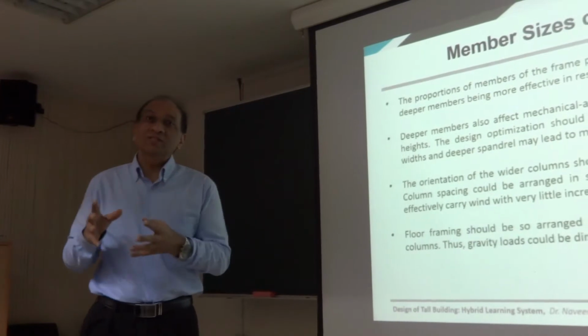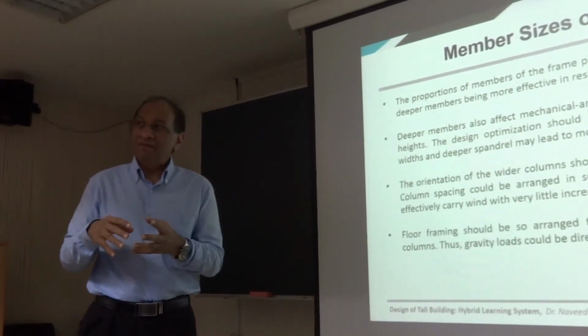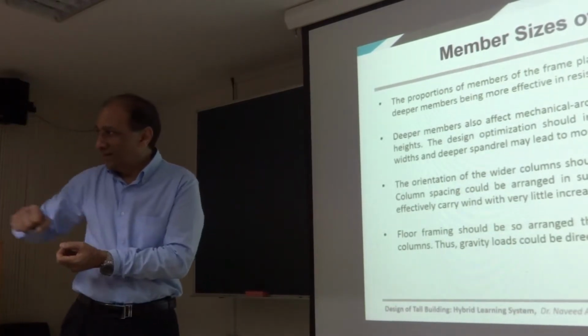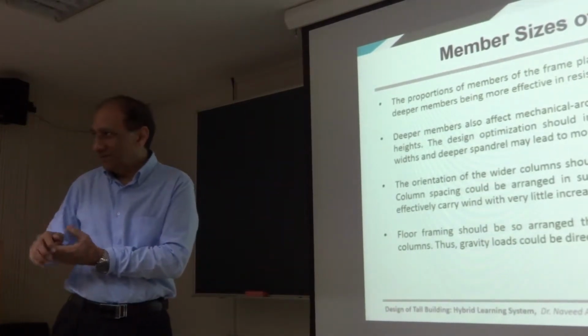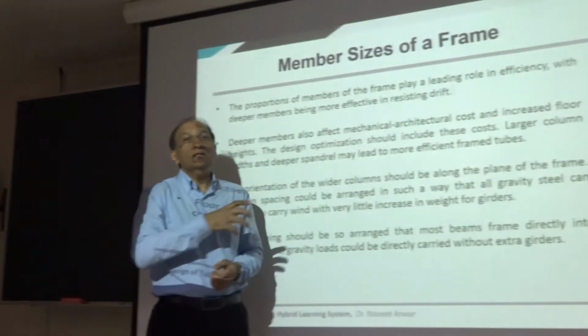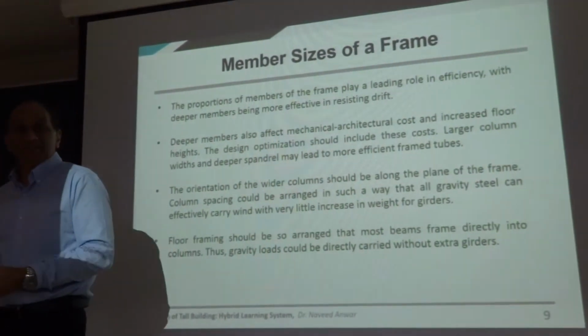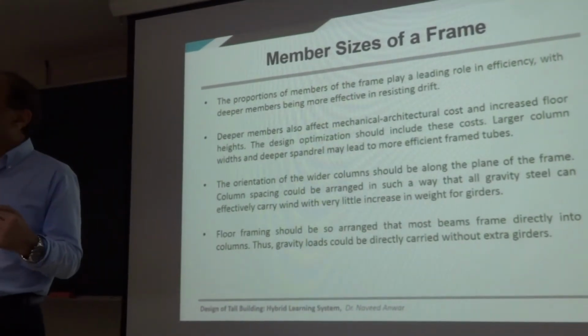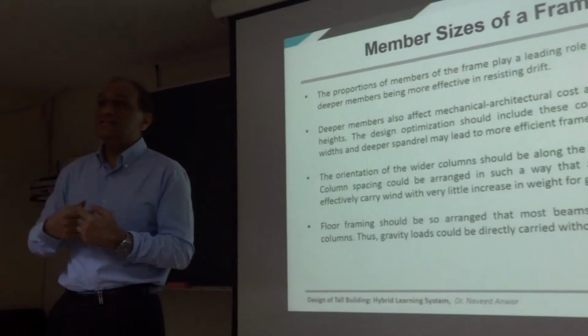So mentality has to be changed for tall buildings, because everything is a game of number of floors, floor area, sellable floor area, right? So priorities for structural system selection change. What you will do normally in a small building does not work in a tall building, and that's something that you need to remember.